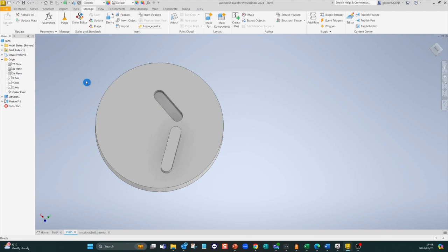Now, the reason why I wanted to show you guys the errors and the issues with the sheet metal environment, if you guys remember earlier in part 1, there were no issues when I converted it to the sheet metal and placed the eye feature. Just keep in mind when you set your parameters that sheet metal also still has its own rules and regulations to follow, and be aware of the specific parameters that you include so that it does not give you the errors in the sheet metal environment. Now this is from the part modeling environment.